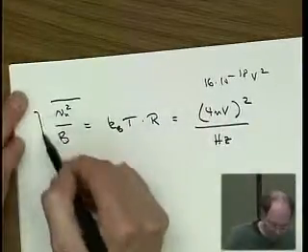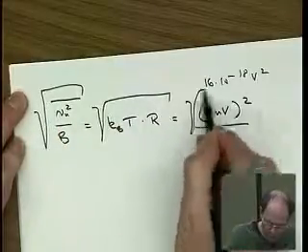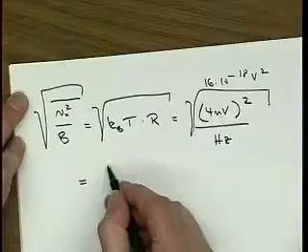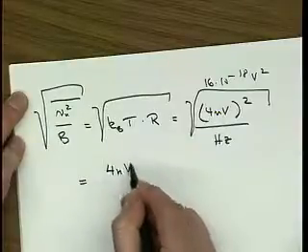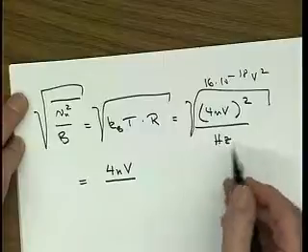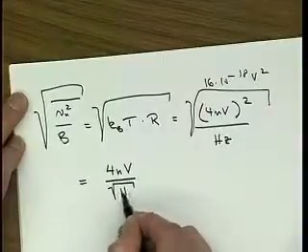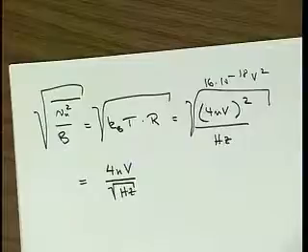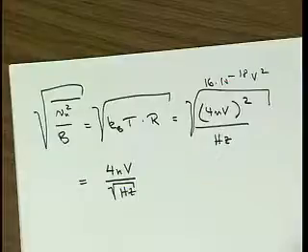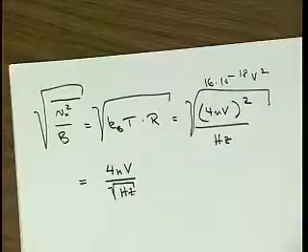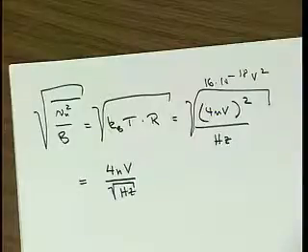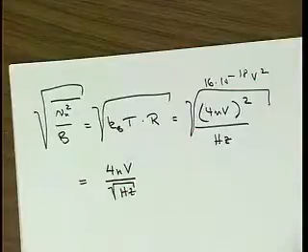Okay, so we normally take the square roots of this, and then we get 4 nanovolts. Now we have this bizarre thing that we have to take the square root of hertz. So we have these very bizarre units for noise, and if you go into the data sheet of an operational amplifier, then lo and behold, it specifies the noise of that op amp in nanovolts per root hertz. If it has only 4 nanovolts per root hertz, then this is a mighty good op amp, at least as far as noise is concerned. More typically, it will probably have 20 or 50 or 100.